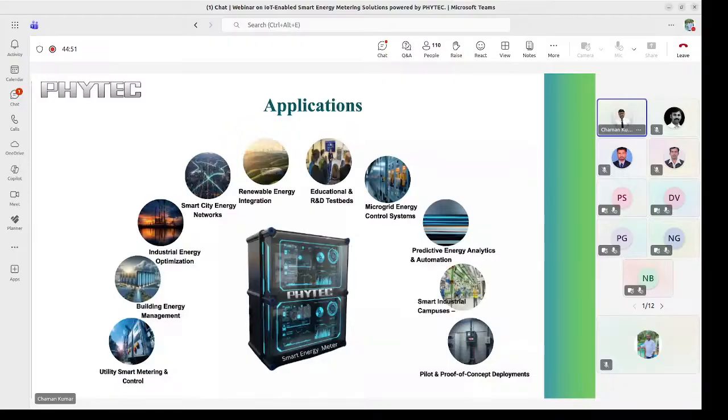Now this IMX6UL needs power, so from the power supply 3.3 volt will come over here. The voltage regulator will just give whatever voltage is needed. Suppose 1.2 volt, it will give to this IMX6UL SoC, and then the DDR memory also requires some voltages other than 3.3 volt, that is also given by the voltage regulator. Then EEPROM memory is available, Ethernet, and NAND flash for flashing the code. So all these things have already been explained.